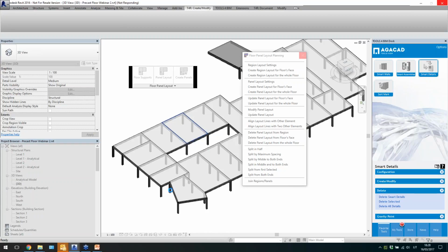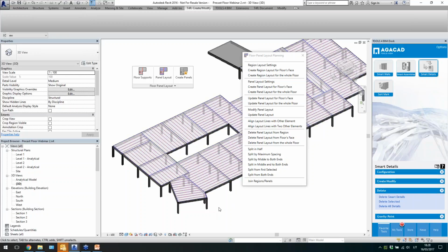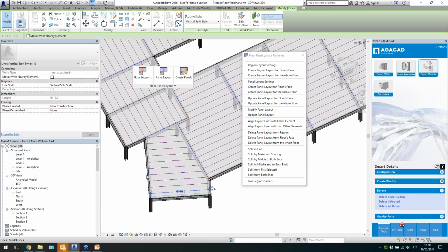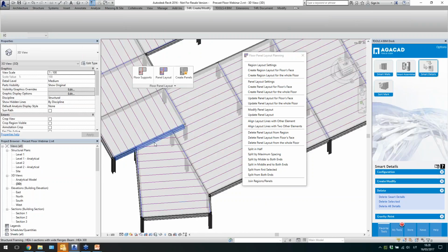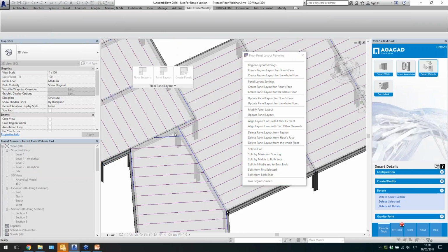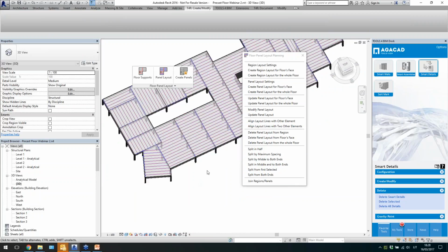So I have different regions, right, in different ways. So maybe I just created a bit of a different shape. I just wanted to test on different situations. So yes, now it's a live demo. Okay, let me get back to Revit, and let me see. So these lines are good. They're just going straight to this one. Maybe I just don't want to have my hollow-core slab like this, so I can just join regions, right, to make it as a massive slab or just a cast-in-place unit.